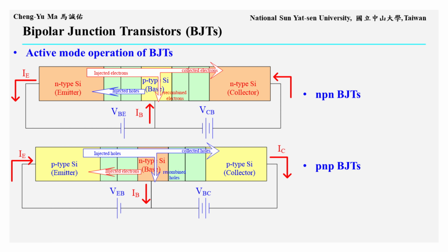The electron current mainly occurs at the base emitter junction, where electrons are injected from the base into the emitter under forward bias. Therefore, in a PNP BJT, the emitter current IE is defined as flowing into the terminal, while the base current IB and collector current IC are defined as flowing out of the device. Overall, NPN and PNP BJT devices operate by the same mechanism. The differences are the carrier type and the corresponding current directions.